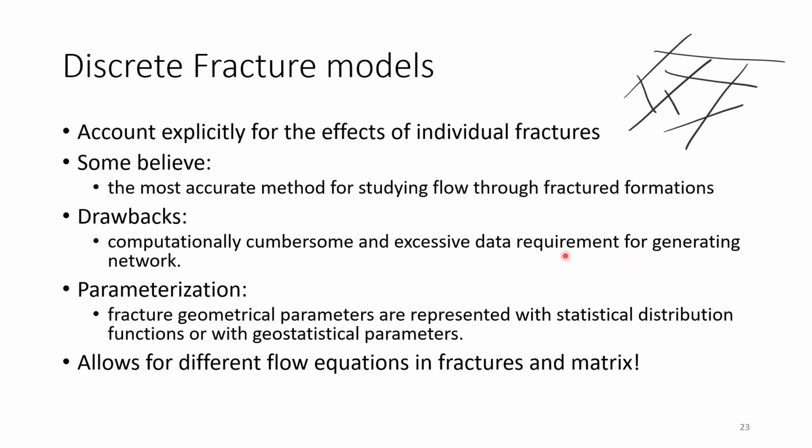All right, remember what I already said: it can be computationally cumbersome, or you have quite a high data requirement. But yeah, you can really study the flow in individual fractures, and you can imagine, okay, maybe you have a geological setting where people are unsure whether there is a fault or not. Well, you can run a model, incorporate that fault, and see how your groundwater would develop. You can remove the fault, and you can see how the groundwater flow would develop.